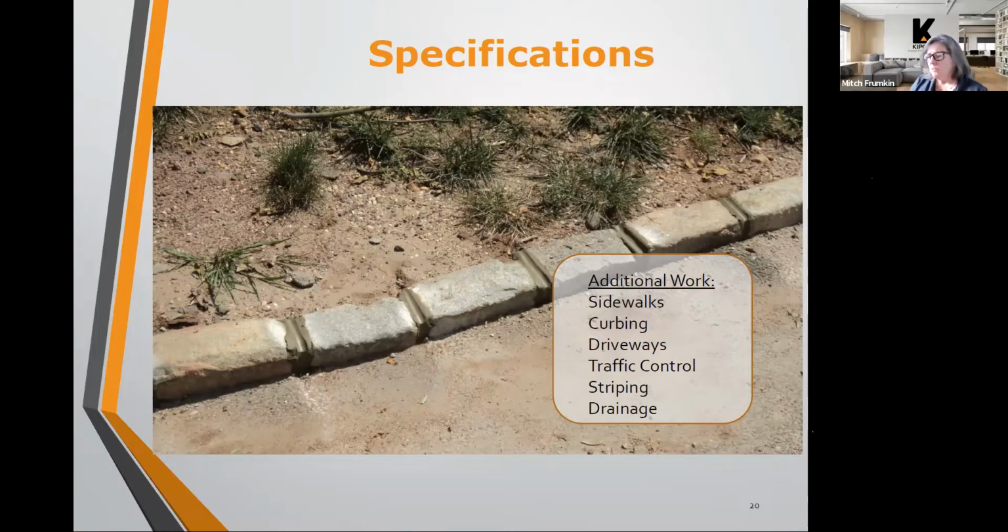So if we're doing a pavement project where there's a lot of clay, we may specify what's called a capillary break, like some stone put underneath the pavement that allows some voids and some drainage relief between that impervious clay layer and the asphalt above, so that you don't have water sitting directly against your asphalt, between the asphalt and the underlying soil. So yes, very good question.